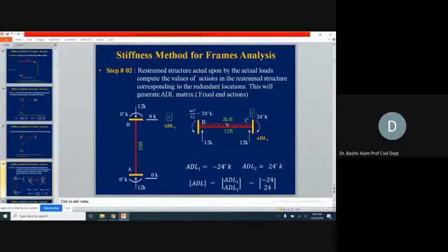So 12 times 2 is 24, divided by 2 is 12 kip. This is how we are getting 12 kip. You can verify this: WL squared divided by 12 becomes 2 times 12 squared divided by 12. One 12 is going to cancel with this 12, and 2 times 12 becomes 24. So already it is verified now.